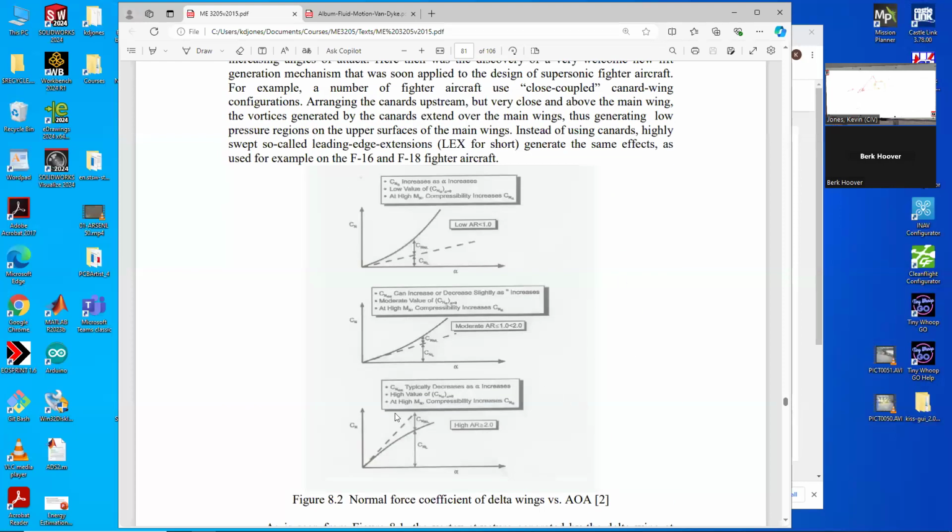This is all subsonic. All these vortical structures. Once we go supersonic, all that goes away. And now each section of the wing is sort of independent. You can almost use a strip theory approach, where you do a 2D solution on each strip, and add them all up. That's not entirely true. On the lower surface, you'll see there's some flow that starts to wash out on the inside. It's nearly separate. And then you'll just get a big shock off the top. I'm sorry, off the bottom, big expansion wave off the top.